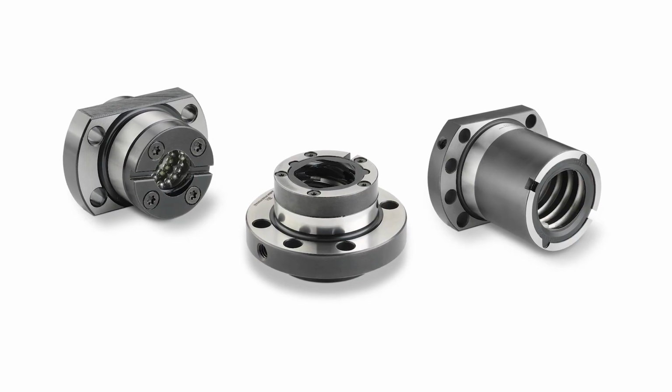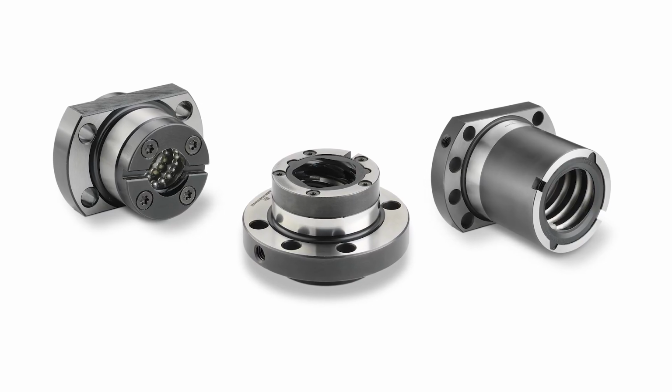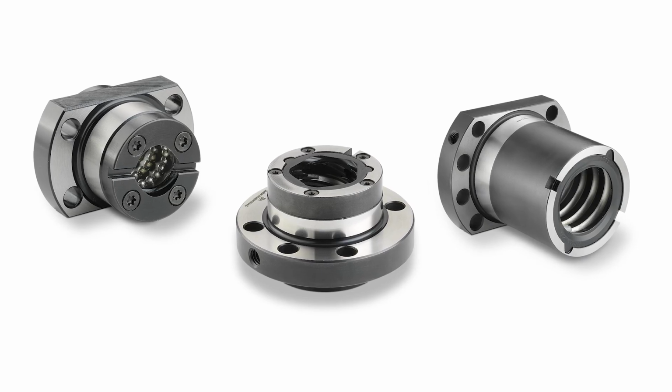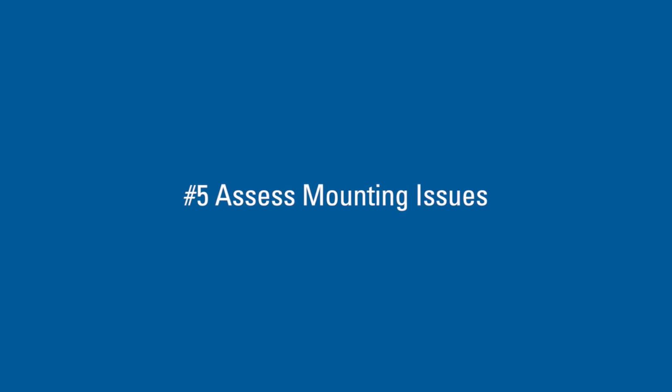Preloading eliminates axial clearance, which increases stiffness and improves repeatability. However, it does not affect accuracy. Preloaded ball nuts are available on select Thompson precision screws and cost more due to complexity, additional machining, assembly, and verification. Assess mounting issues carefully.